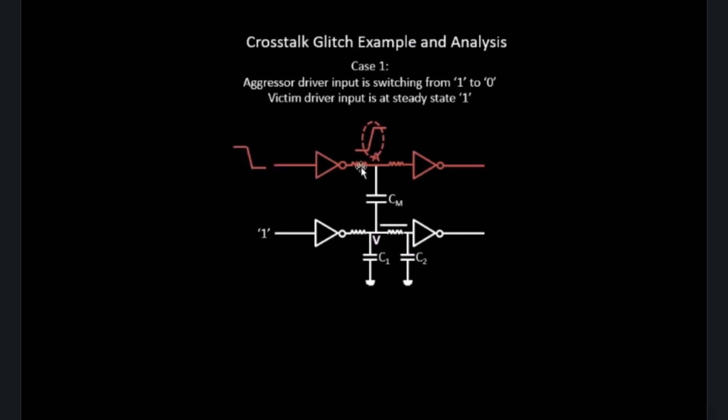So basically, whenever we say that it is switching from logic 0 to logic 1, it is depositing charges on the capacitor that it sees at this node. And it also sees this capacitance as well, and this capacitance is just like a leaky bucket with a hole, because it is not grounded. So you see two types of capacitance over here. One is the capacitance which is completely grounded, the ideal ones, and there is one more capacitance which is between these nets. So these are not grounded, but connected from one net to another net. Let's call it a bucket, a leaky bucket.